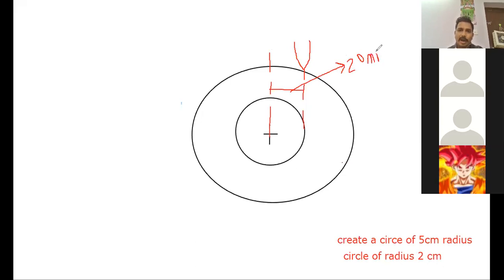The second thing we have to do is, again the same counterparts will act. We have to divide the circle into 60 degrees of outstroke, then 30 degrees dwell, then again 60 degrees of return. So I would place a line here and divide this into 60 degrees.